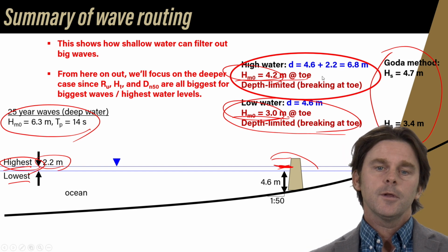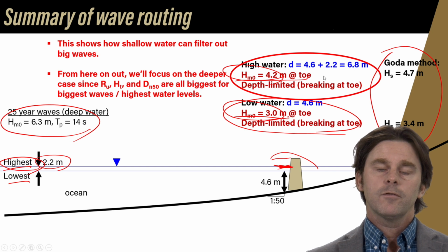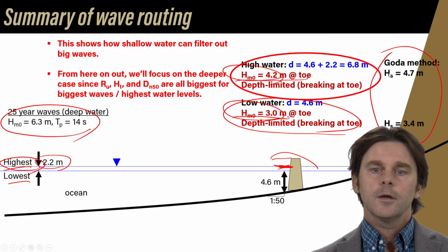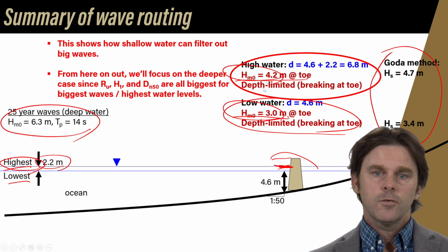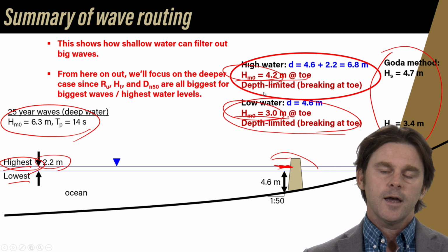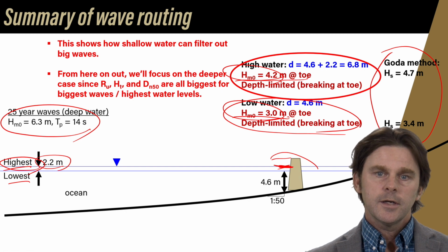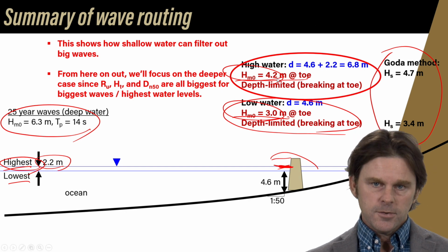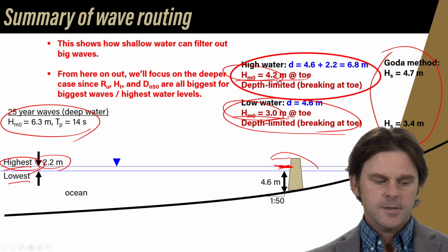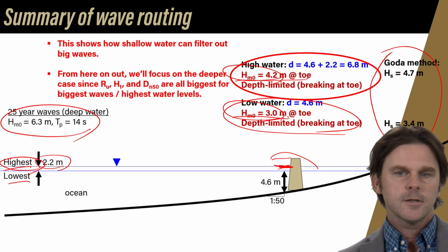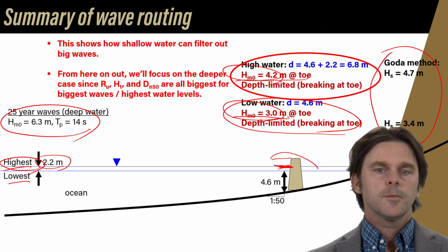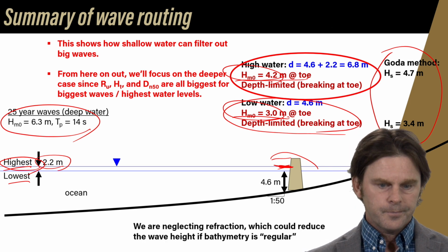It depends on the formula that you're using and what that particular formula wants. I'm not going to be too picky about what we're going to be plugging in. We're just going to use these foreshore wave heights over here for the design. But in actuality, certain formulas want the significant wave height and certain formulas want the spectral significant wave height, which makes things kind of complicated and gets us into the weeds, and I'm trying to highlight the big picture stuff here. So something to keep in the back of your head.